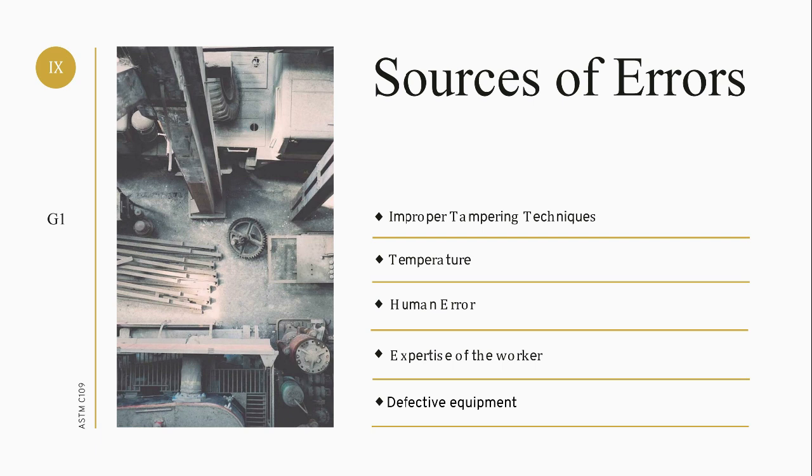Third, human error. It is expected that the mortar sample would have a higher average compressive strength. This could have been a human error related to 10.4.1 of ASTM C109, which involved mixtures of the sample.